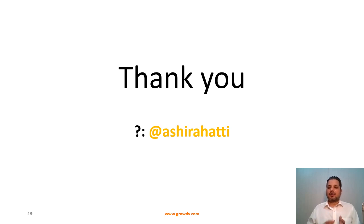We indicated that we can do polling as well as an interrupt based flow, and then we looked at the test cases present in this particular test bench, and selected one of the tests, the word format poll test. The intent of that test was to randomly program an LCR value and then do 2 character transmission and 2 character reception.